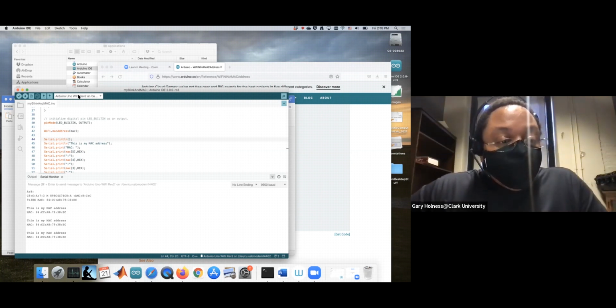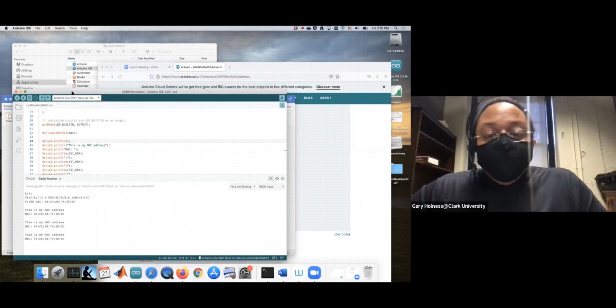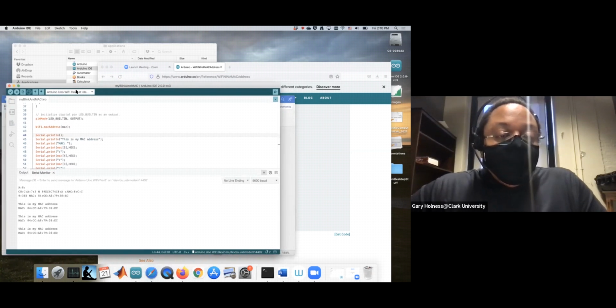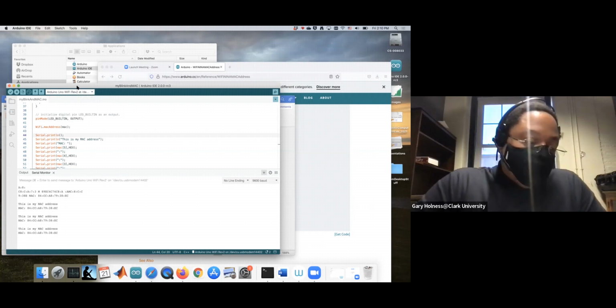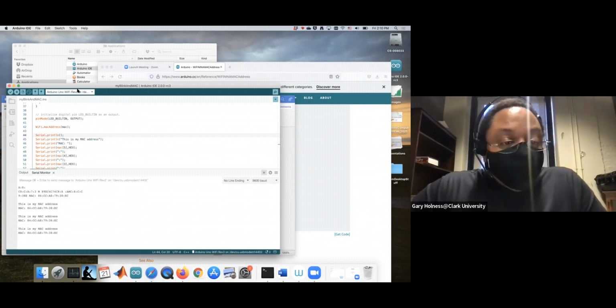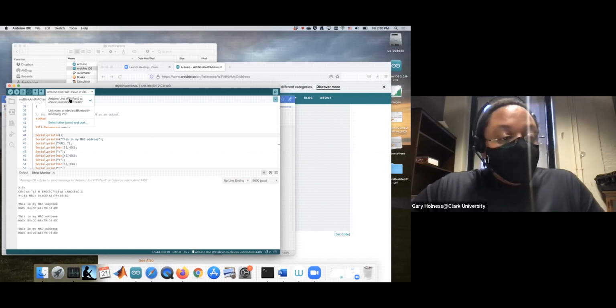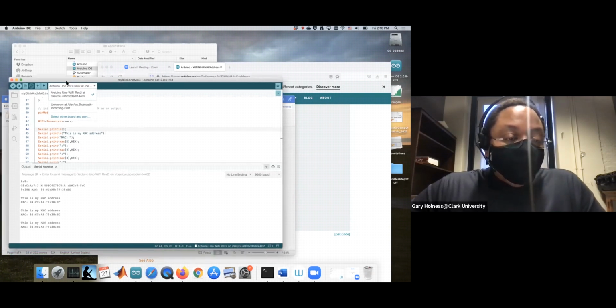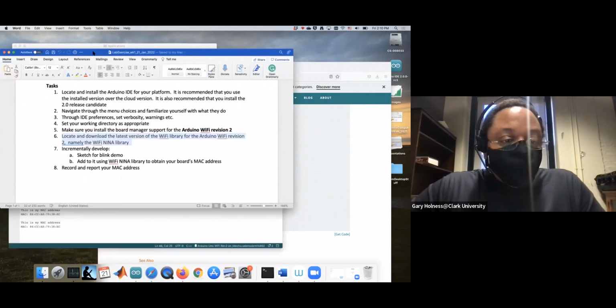And so there's a drop-down list, you can see here, that will be an enumeration of all your ports. Now, on Windows, it might be COM1, COM2, COM3. On Linux, it would be a device file. On Mac OS, since it's Unix, BSD Unix underneath the covers, it will also be a device file. So it's really important that you select the proper port for talking to the board from your IDE, but make sure you follow the instructions, the steps.